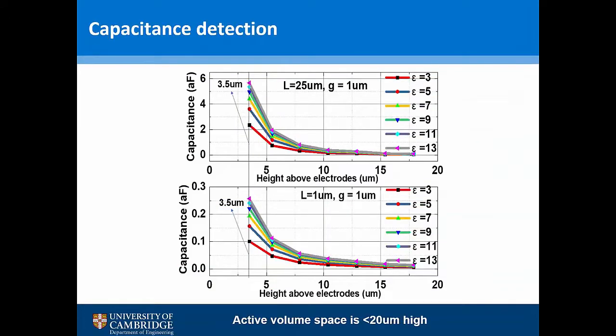Then, like I said earlier, we did the capacitive detection for that, and we moved the particles to be only as close as 3.5 microns. Of course, because the particle diameter is 2 microns, we didn't want a situation where the position says one micron, which would mean the particle already penetrates into the electrodes, which doesn't happen in real life.